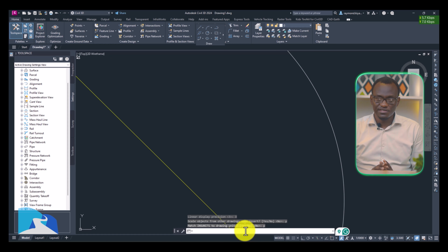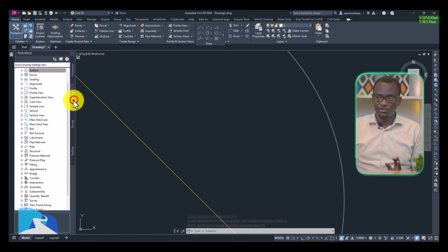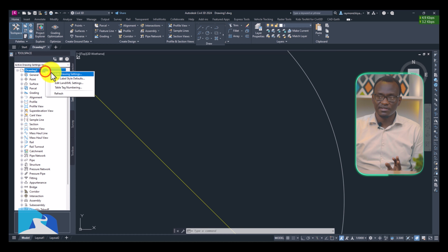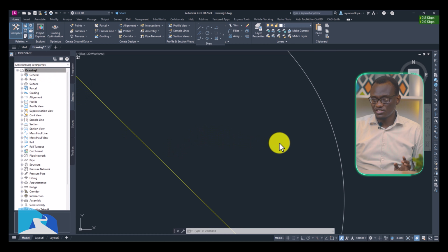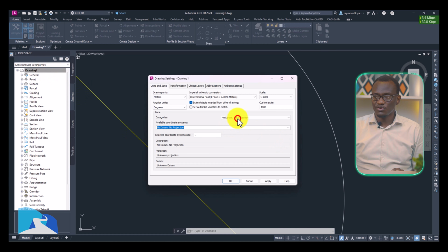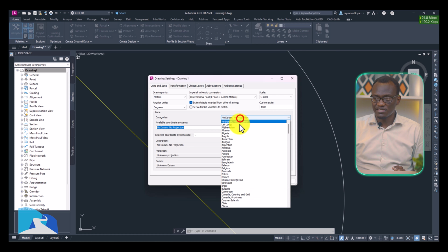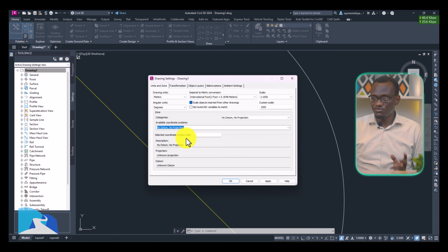Coordinate systems is another one. Always make sure you have the right coordinate system for this. I feel this is a no-brainer, but it's a question that always comes up. Someone not putting the right coordinate system, depending on, there's the Google Earth and then there's the native coordinate system that you're working from and all. That I find is very, very important for someone to know.